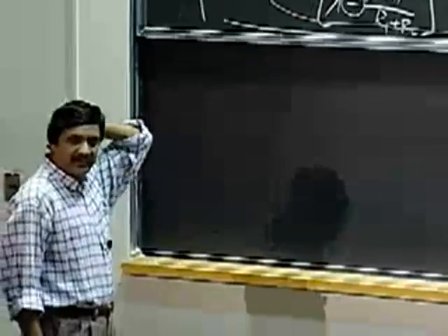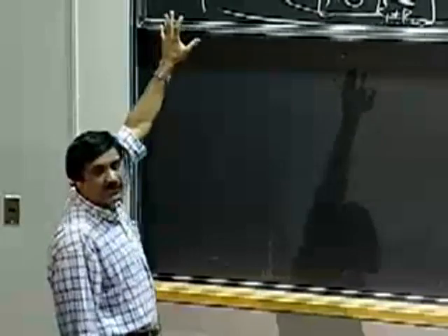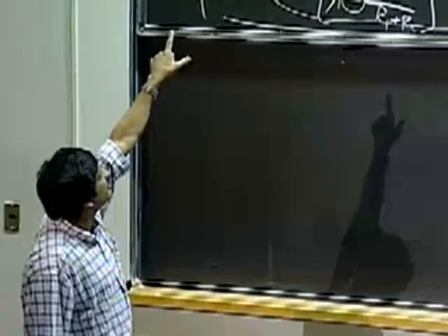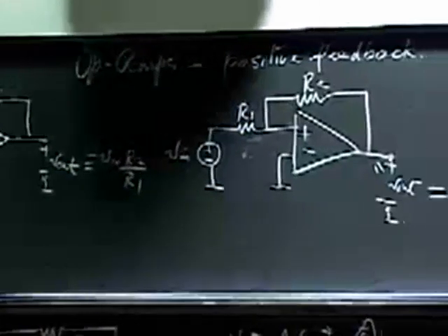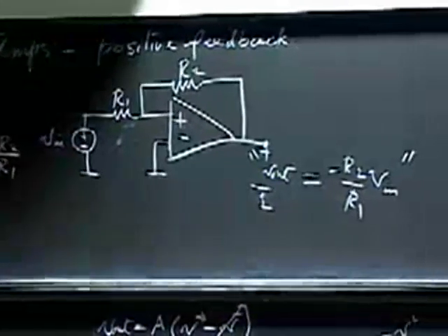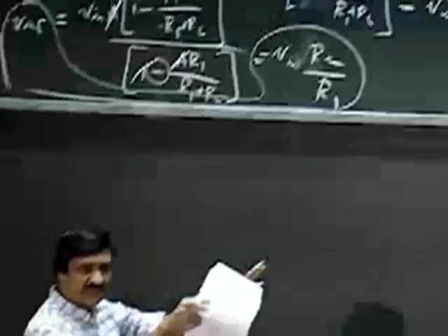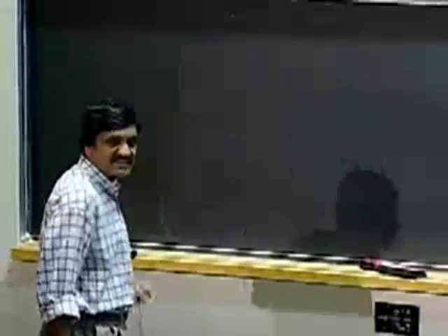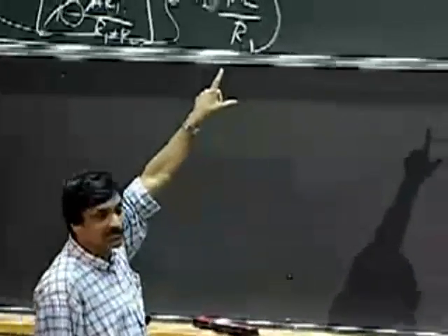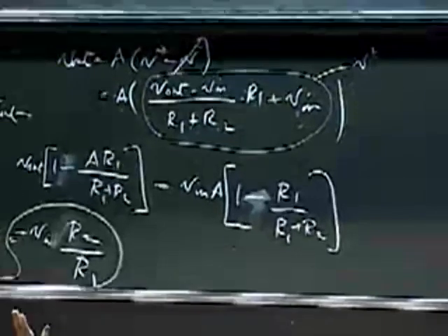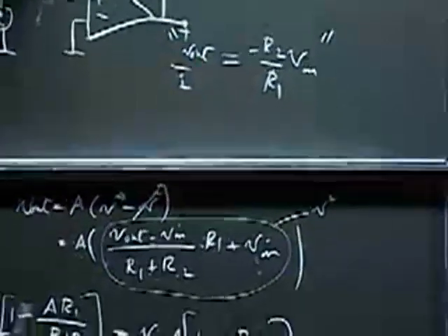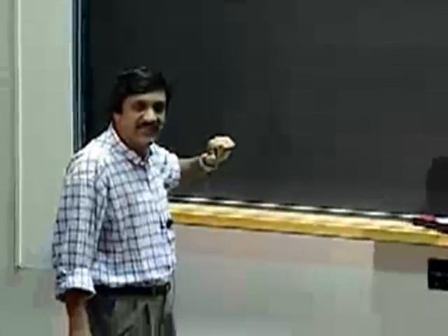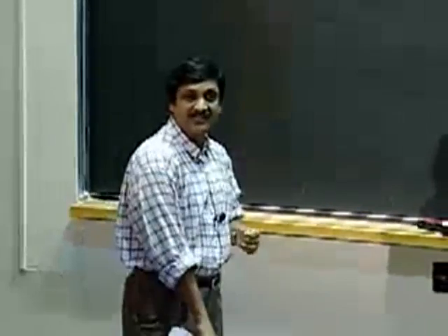So what we've done so far, if you stare at these two panels here, first of all, we know that the inverting amplifier has the expression for V out up there. And through this laborious exercise, we've also shown that even with positive feedback, if I take a static view of the circuit, if I take a snapshot of the circuit and simply analyze it as a static circuit, I get the same expression for V out. But what we're going to do is, when I explain to you that, look, a small perturbation in V out is going to drive the op amp to the positive and negative rail.